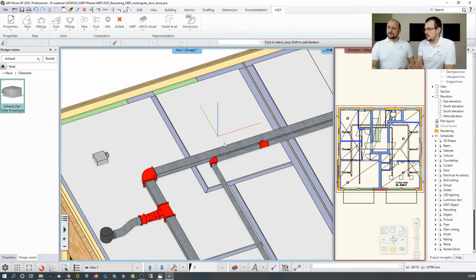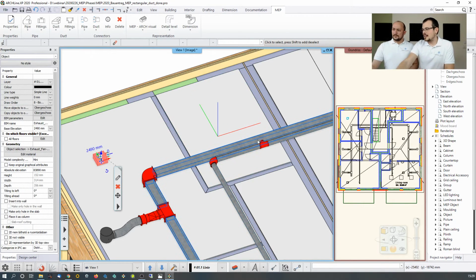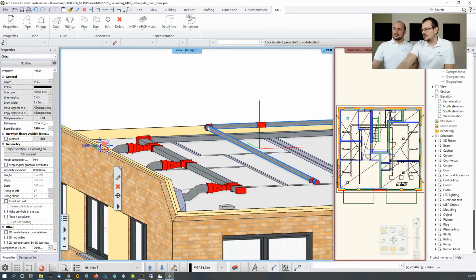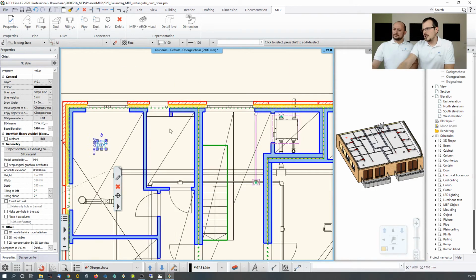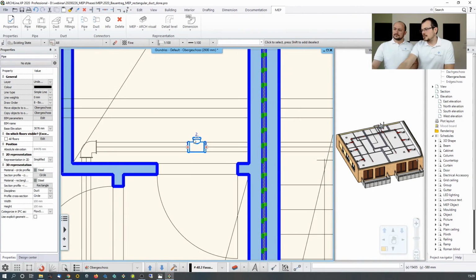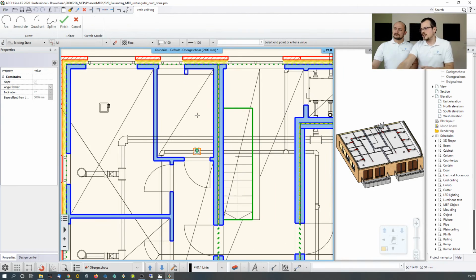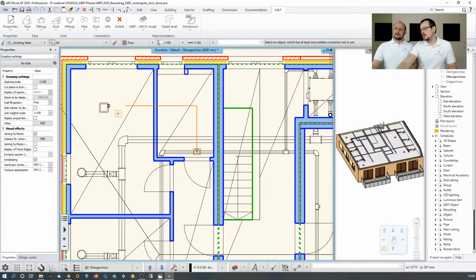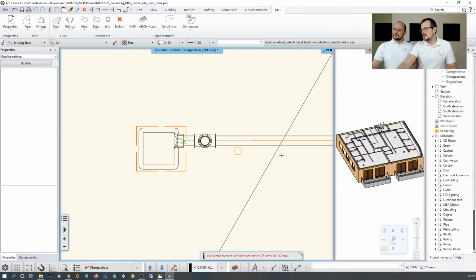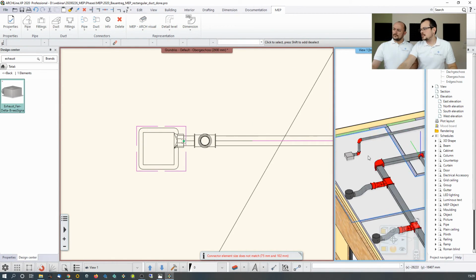That's right. And I'm going to use the same method to connect this T with this element. But again, the problem is that these guys are on a different level. Yes. So I need to bridge that gap somehow, and I'm going to go back to the 2D to do that. Things start out manually. So I click on the port and I start drawing, and by hitting the shift key I can tell the software that I want to draw it until this point. And I'm going to go a little bit closer here, and then I'm going to use the auto connection or auto routing to click on the element, and then the connection is solved by itself.